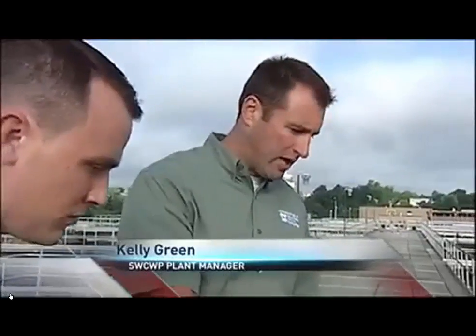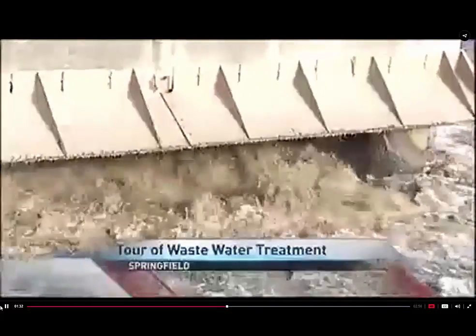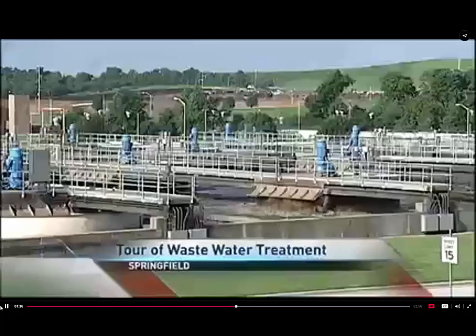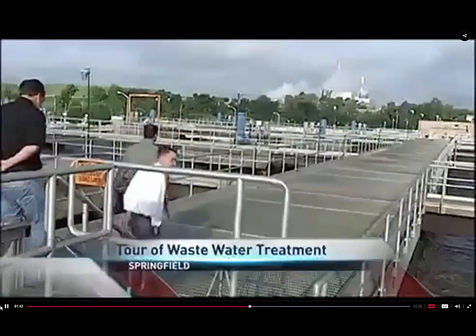So as you can see, after the water comes out of our headworks, it flows in here. This is still the raw wastewater. From here it's going into our aeration basin, and this is where the treatment actually begins. So basically what we do is we create a specific set of conditions to cultivate a specific type of bacteria to consume the waste and to perform the treatment.